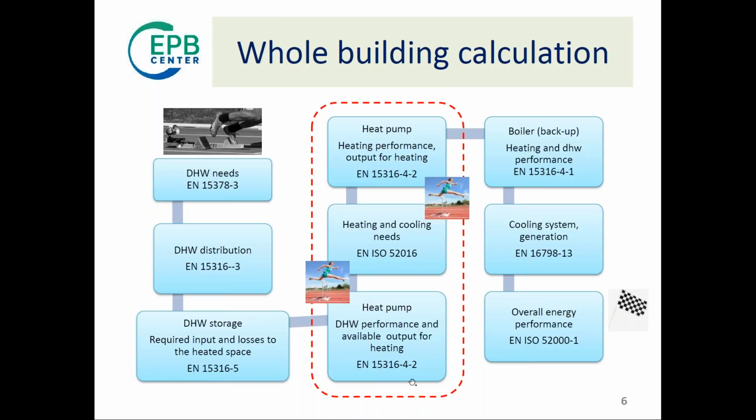And you might also calculate your generation system just for domestic hot water, not yet for heating, because you don't know yet the heating needs. So you can pass the information to the building needs calculation: I only have some amount of heat available because, for example, I already had to satisfy the domestic hot water production, which is what happens in reality when you have a priority for domestic hot water. Of course, if they are separated, this doesn't apply, but very often you use the same generator for both heating and domestic hot water. And given this, you can calculate the needs, now knowing what's available. And in this case, then you proceed when you know the needs.